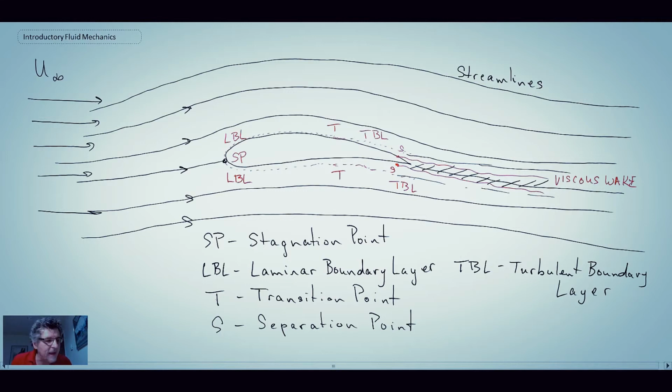So that is an example external flow, and what we'll be doing in the next few lectures, we're going to be looking in great detail at what could be going on in this layer right here if we zoom in. And what you would find, that is the boundary layer. What we'll find is we have the no-slip condition on the wall, and then as we go out, we get to the free stream. So we'll have some external flow out here, and then we have a velocity deficit region because here we have no slip.